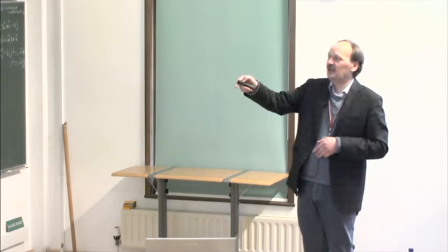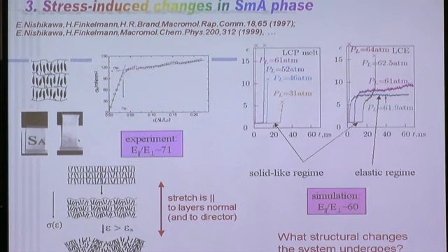So what we did, we just applied a constant uniaxial stress, and we indeed have two typical regions for the elastomer. In the case of the melt, the sample is kept for some time and then is destroyed. But for the case of the elastomer, we have this nice elastic regime where it withstands the pressure after this flat region. And one can estimate the anisotropy of the Young modulus here, comparing this to strains at the fixed stress, and we have something like 60, which is also comparable.